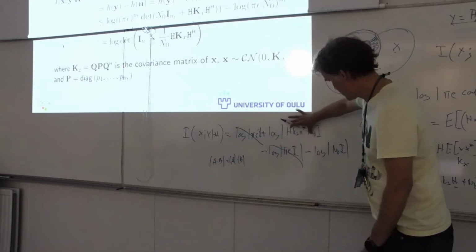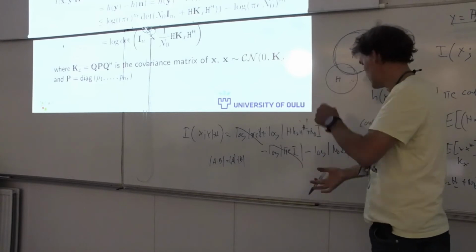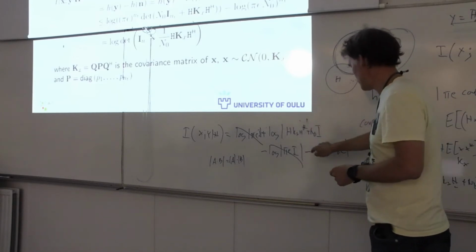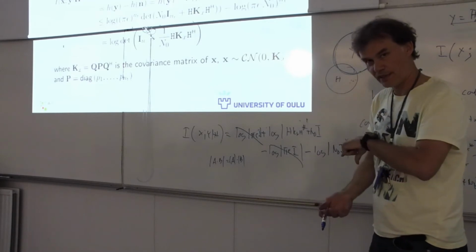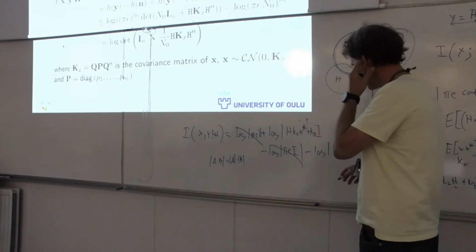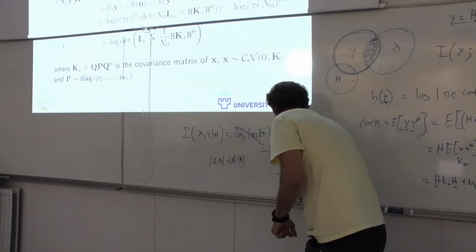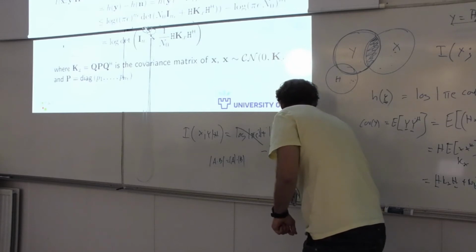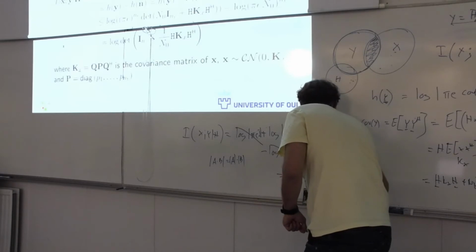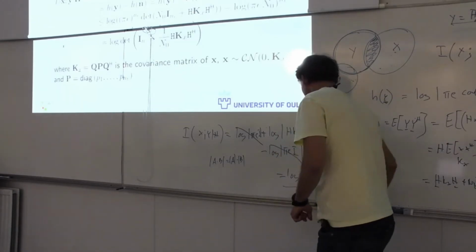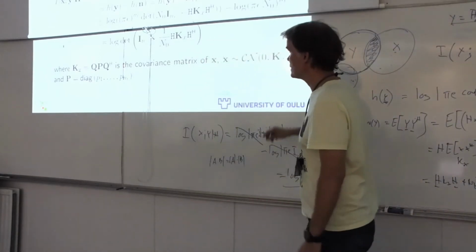And this one goes inside. So log minus log is the log of the ratio: log determinant A minus log determinant B is the same as log determinant of A divided by B, and then we can take that inside and so on. So in the end, we have log determinant of I plus 1 over N0 H Kx H Hermitian. That's the general capacity formula for the MIMO model, right?